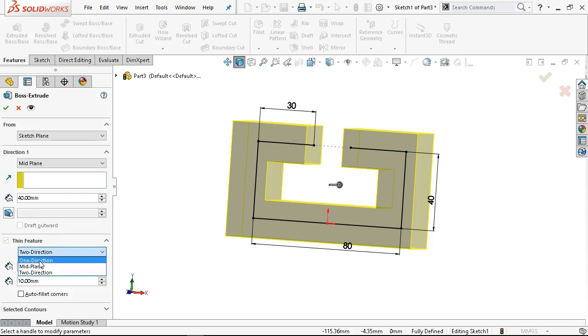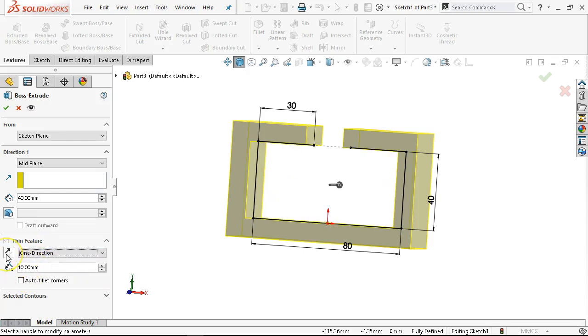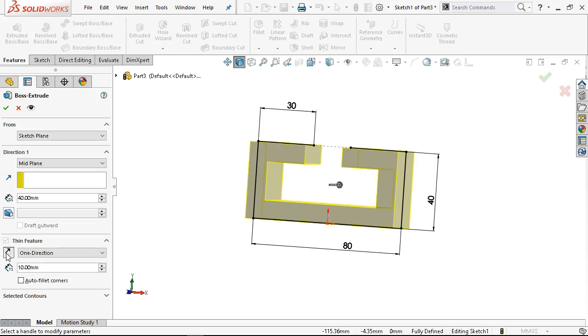So that would have stretched it up to 20. And we have the toggle button to reverse the direction. That was what I was looking for. And then if this is more along the lines of sheet metal, we can tell it to auto fillet, and it will do 5 millimeters on the interior and plus 10, 15 millimeters on the exterior. All right, don't want auto fillet, but there are places where I've done basic architectural extrusions or a bent item that doesn't really need to be sheet metal, but needs to have the fillet in place.